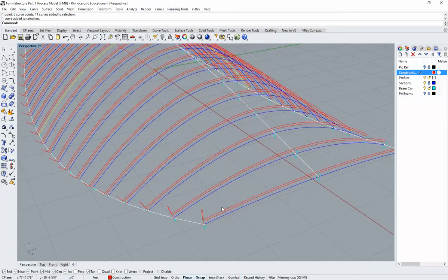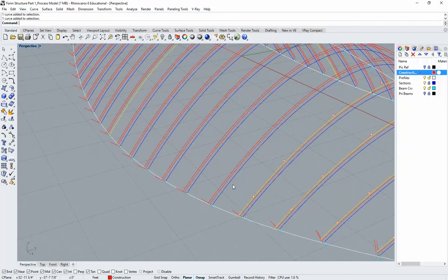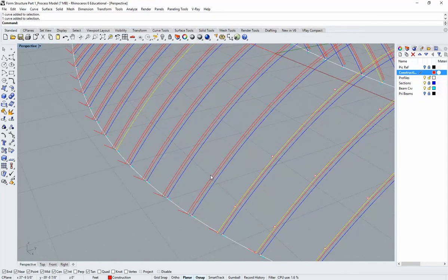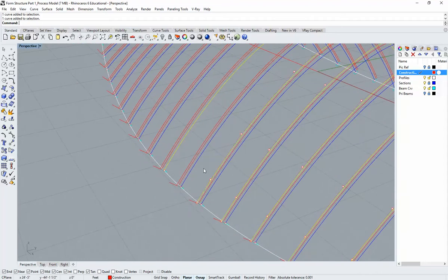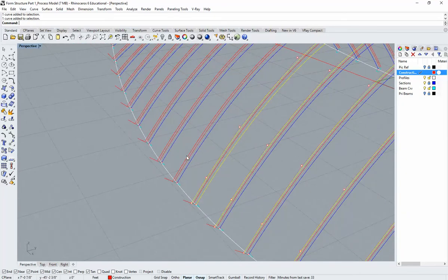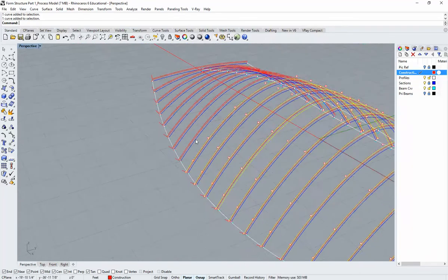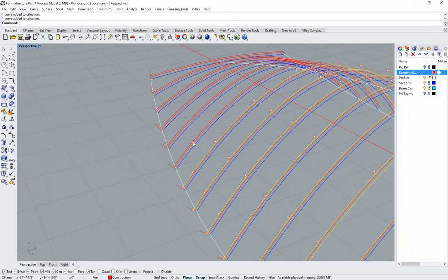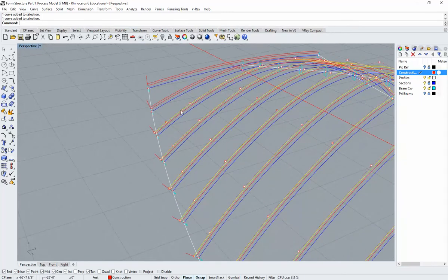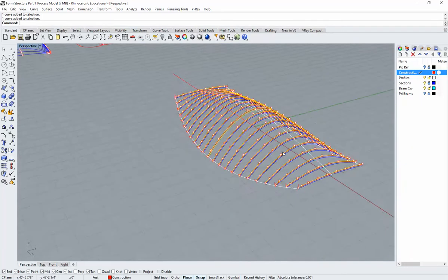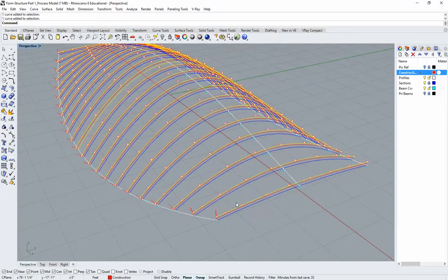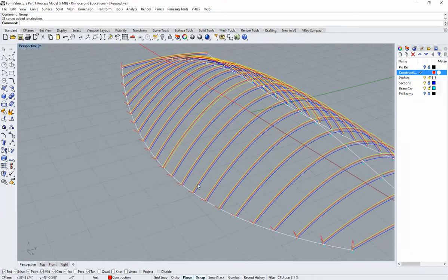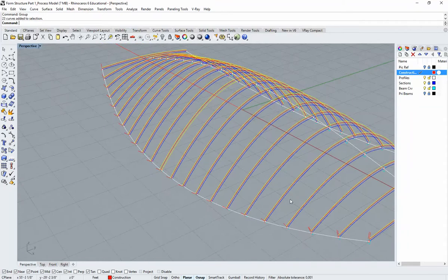All right, the next step is going to be to divide that upper offset, the top one, because that's going to end up being the center of our secondary structure. So I'm going to select all those again, and if you're clever, unlike me here, the last time you selected all these, you could group them. I was too lazy and I didn't, so now I have to reselect. So if we group them, it'll be easier to select later. So you can go ahead and group those, that's fine. So now when I select that, I select them all at once, which is kind of useful. So I typed in group and I grouped them.